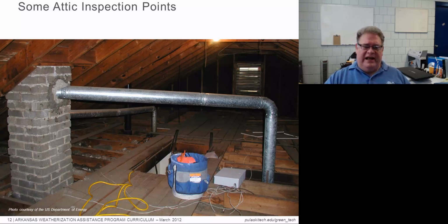We have a floored attic here. So what does that mean? We don't want to just loose fill underneath that floored attic, because what's going to happen, especially with cellulose, is you're going to get settling of that cellulose, and then you're going to have gaps in your insulation. So underneath the floor, we may blow 3.5 or 5.5 inches of insulation, but if we don't dense pack it, then we're not going to prevent settling of that.